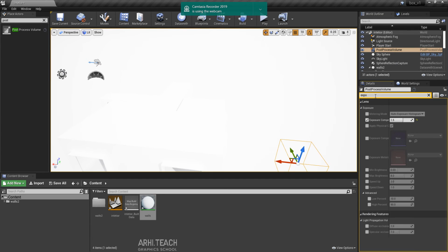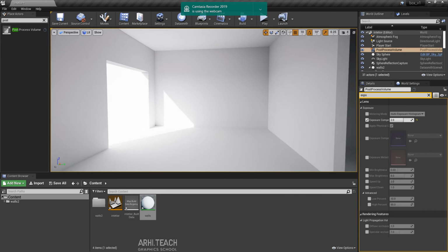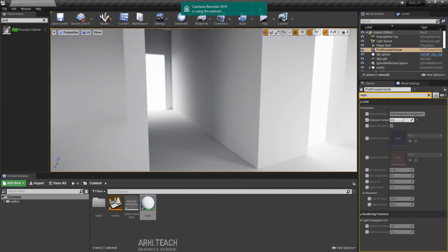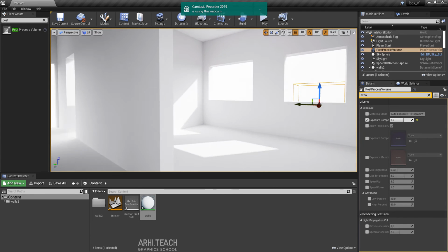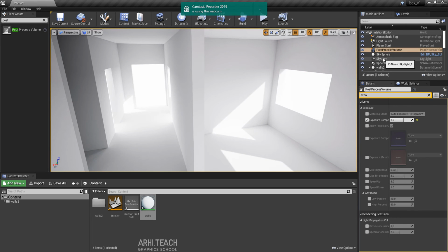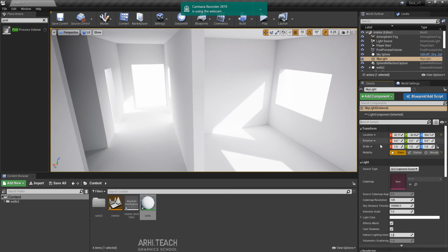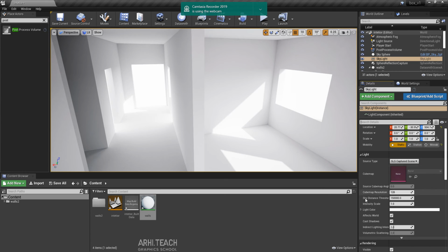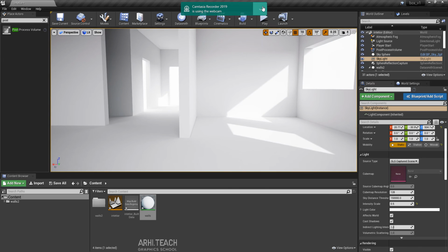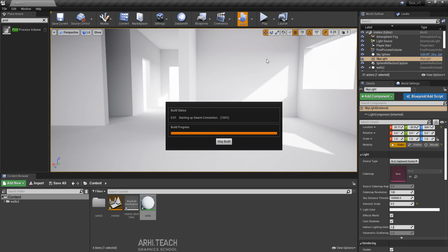We return post-process. Set the exposure of 2, because actually these settings always worked. I found them once and now set them. Of course it depends on the scene, but they really work fine. I usually downgrade skylight. Make sure the static is set. I'll put it at 0.5. There will be less light and more contrasting shadows here. Let's see how it will look.